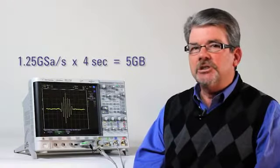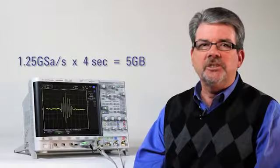With segmented memory acquisition, the scope captured each sine wave burst with high resolution, but didn't waste valuable acquisition memory capturing the idle time between each burst. Capturing 4 seconds of time using conventional oscilloscope memory would have required 5 gigabytes of memory, which is currently not available in any scope on the market today.